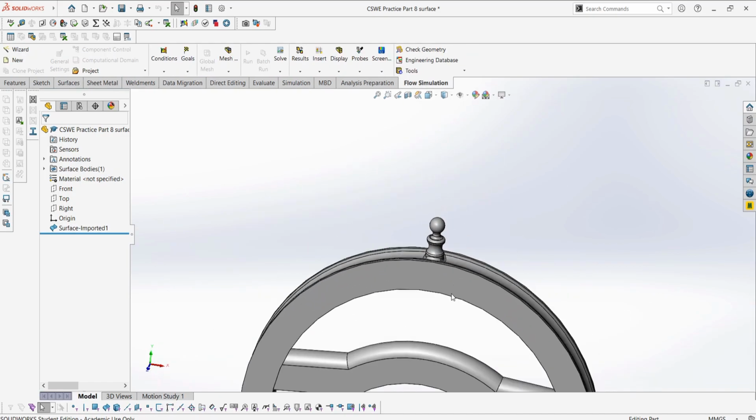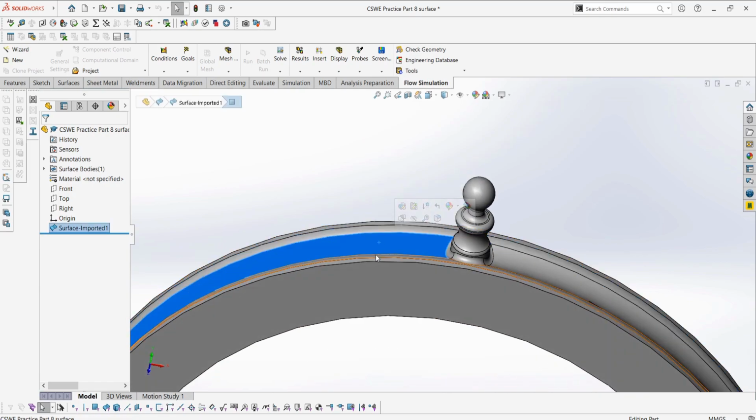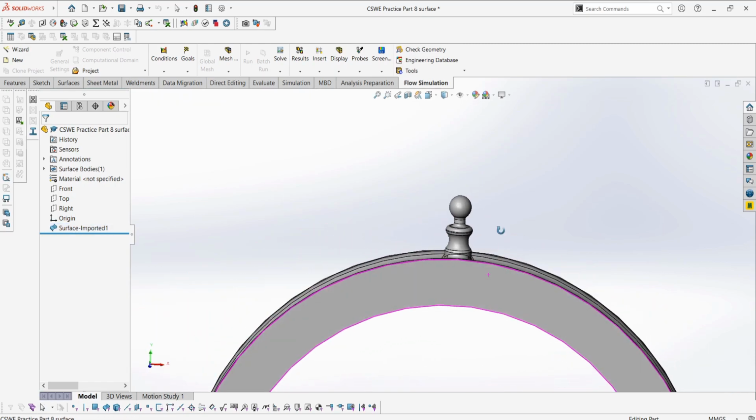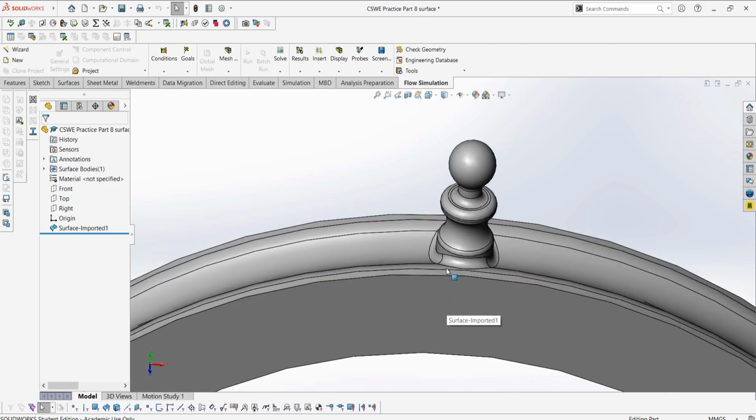So basically what we want to do here is delete this surface, and then use the move body to move this guy 10 degrees this way, 10 degrees that way, and then patch up the surface by recreating it, and then delete the intersecting surface, which should be like below here, because we're going to revolve this guy back.